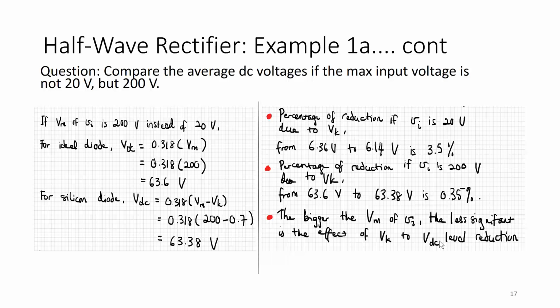So sometimes, even though we know there is a value for the voltage drop, because it's not very significant to our calculation, we just assume it can be an ideal diode. That is just practical, having a ballpark average figure when we're doing practical designs.